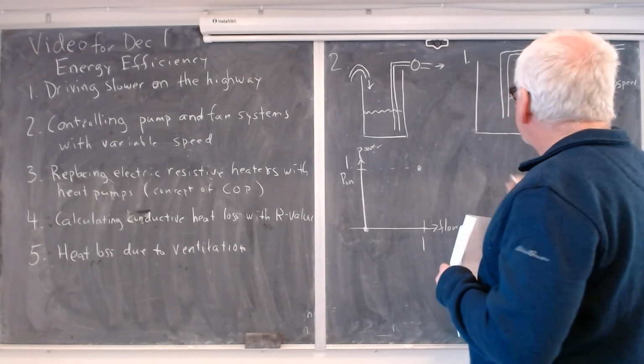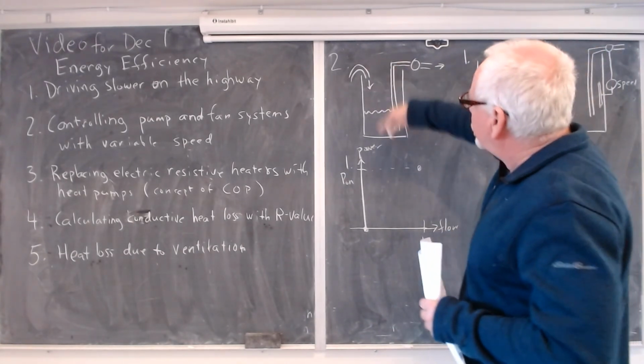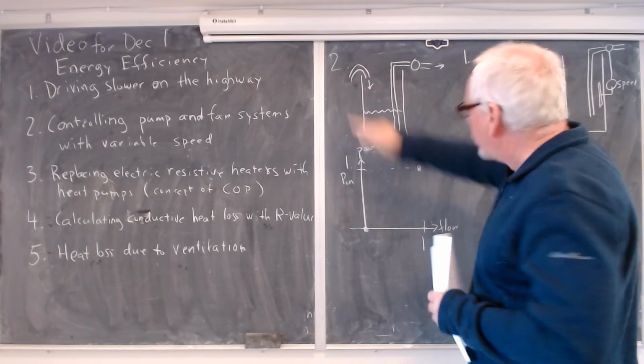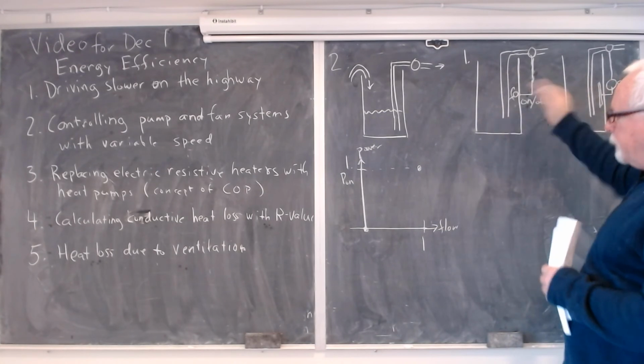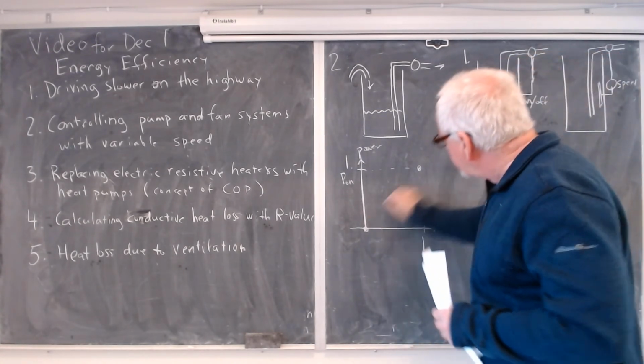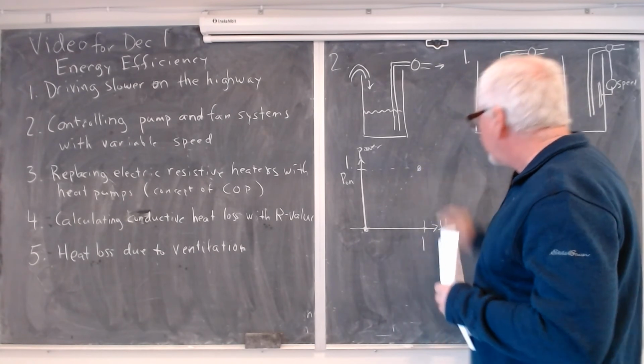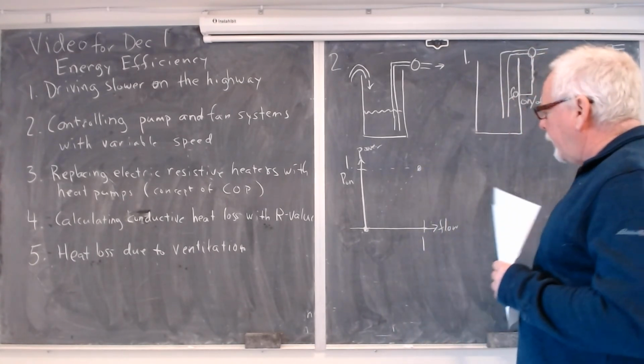And so what happens is that as the water level rises and falls due to this incoming flow varying, the pump turns on and off and on and off, and basically it's going between these 2 points here like that. And so we can draw what's called a load line, which is power versus flow like that.